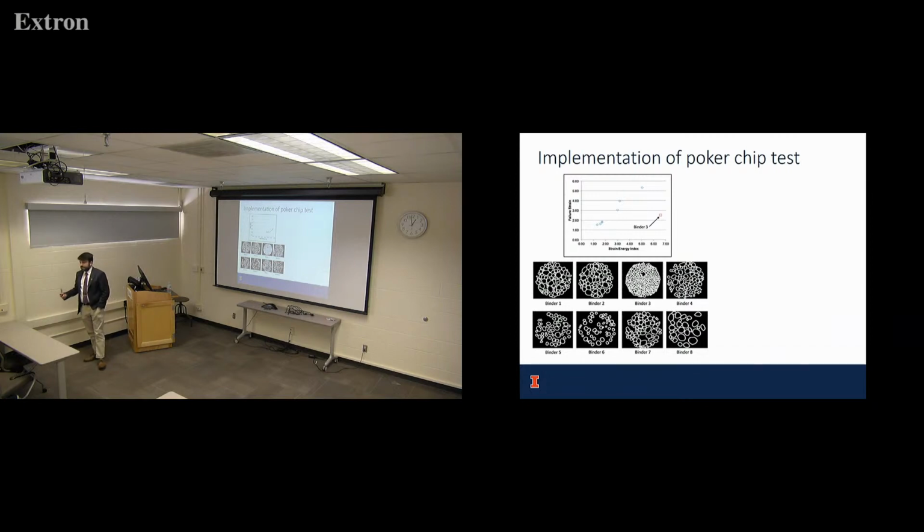So we said, wait a minute, what's happening here? It's passing the spec based on linear properties, but it's got a horrible strength. And so we ran an XRF analysis, and we did find some trace metal content here.